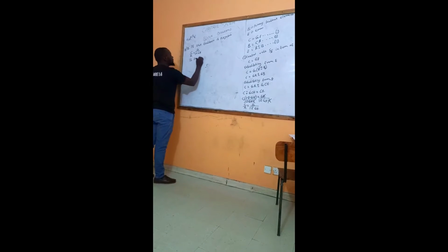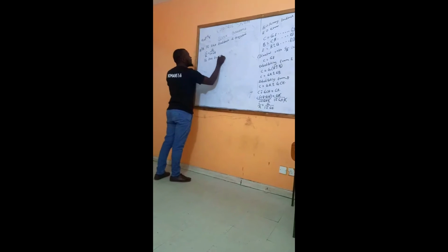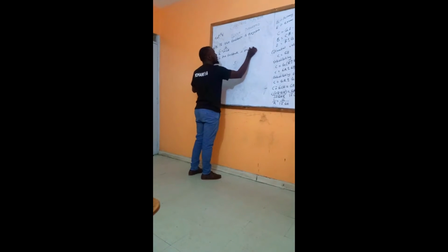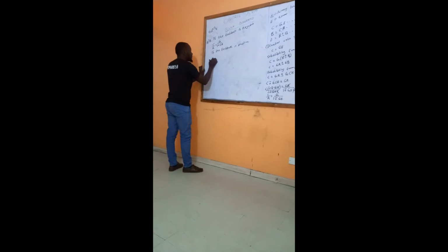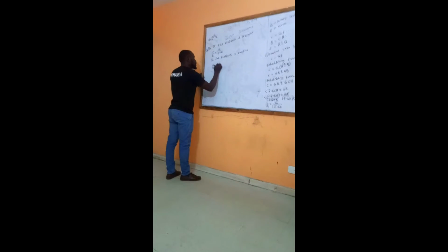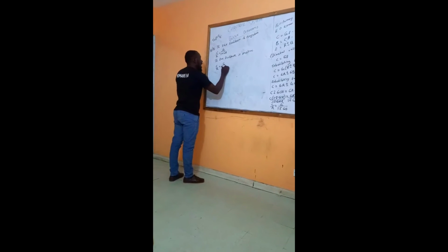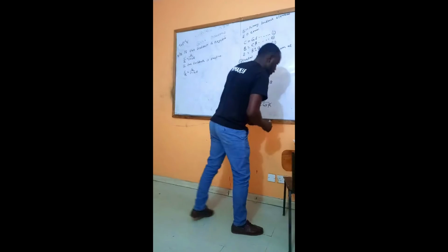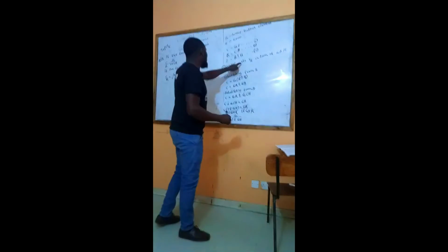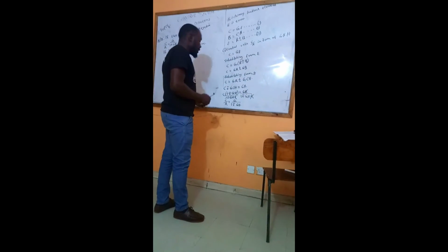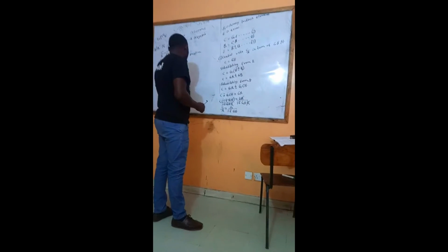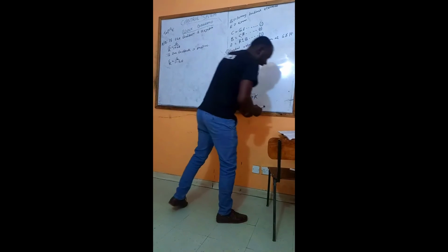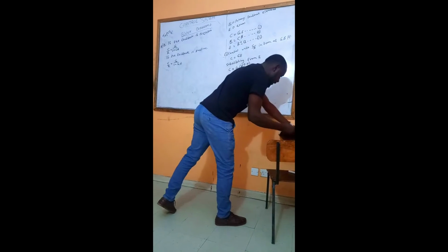And now, if the feedback is positive, what are we going to have? C over R is equal to G over 1 minus GH. So you need to remember this as we continue. Now, we have solved this one, the control ratio. And this formula you will really use everywhere in this topic of block diagram. Let's go to the next thing.